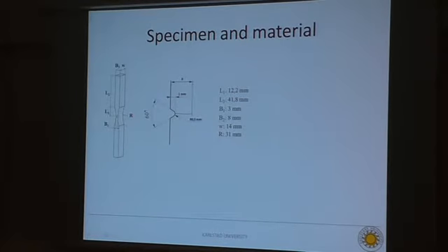The specimen that we are using is a fatigue crack growth specimen for the ultrasonic testing. The rectangular cross-section gives us a plane surface to observe and measure the crack on. The sinusoidal part in the middle reduces the resonance length of the specimen, makes it shorter.